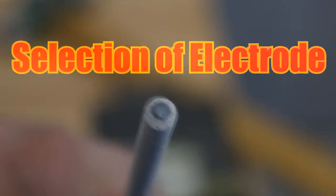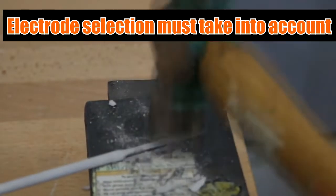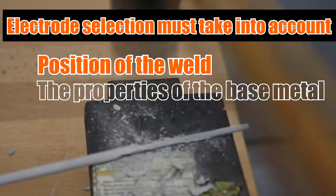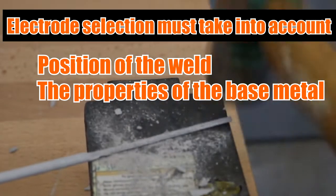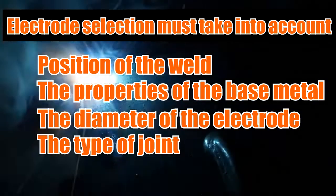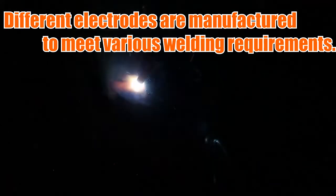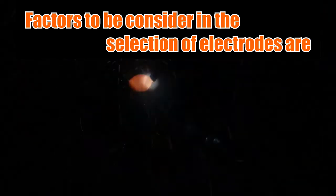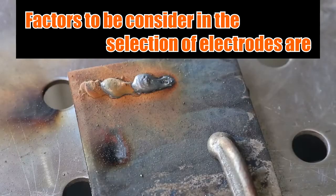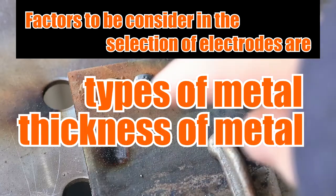Last is selection of electrode. Electrode selection must take into account the position of the weld, the properties of the base metal, the diameter of the electrode, the type of the joint, and the current. Different electrodes are manufactured to meet various welding requirements. Some factors to be considered in the selection of electrodes are types of metals, thickness of metal, and tasks to do.